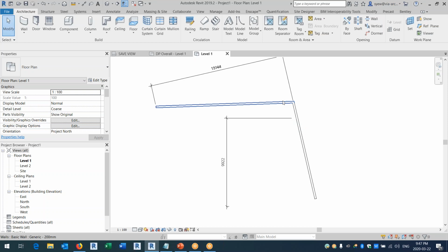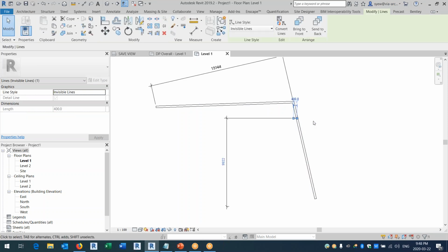I know that most often people have this inclination to ask, why don't we just dimension to the wall? You cannot control, even in a larger project, who's going to be monitoring or moving the wall. So most of the time you have a specific dimension you want to keep, and sometimes junior guys will tend to move it. So just be aware of that. This is a perfect way to create dimensions with a fake invisible line that you can't see.